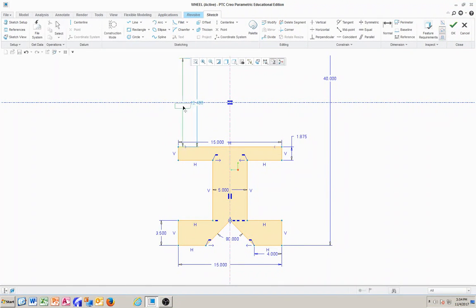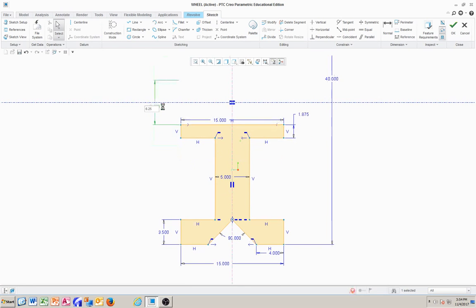And this is the diameter of the hole that is going to be cut, and that should be about 6.25. Okay, 6.25. You might say, how did I get that? You look at the drawing, and it says the diameter of the hole is 6.25. So this thickness here was 10 minus, let me just show you the math in here. I'll say 10 minus 6.25, and then whatever that is, we divide by 2. 3.75 divided by 2 gives you 1.875. It does the math for you.